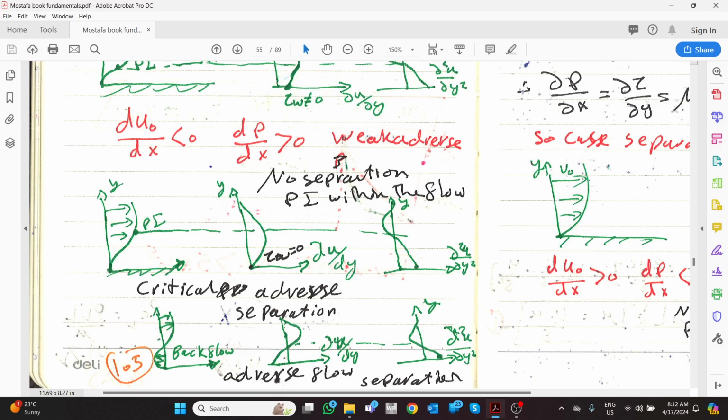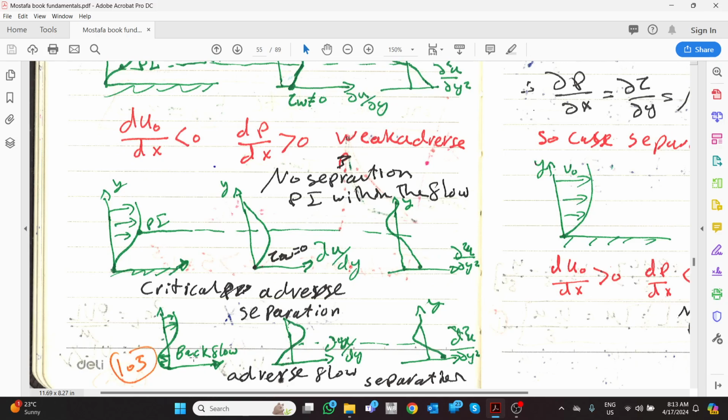Now there is a pressure, so the flow comes like this, which means there is no movement just here at all in the flow, there is no viscosity between this one and the plate, which means there is no shear anymore. This is the critical point. If the pressure increases at that critical point, where du/dy equals 0, there will be a backflow.